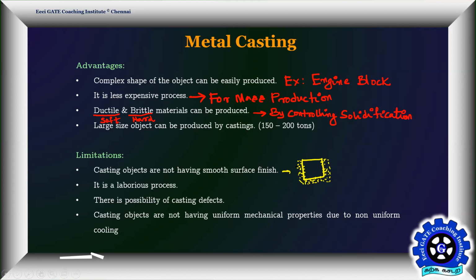Yes, sir, and that's why we even give pattern allowances also because of that. That we'll discuss. Because of these sand particles sticking to the part, you're not having a very smooth surface finish. So what do you do? You take this part out of it and you do grinding, and you get the product to the appropriate surface finish that you wanted to have.